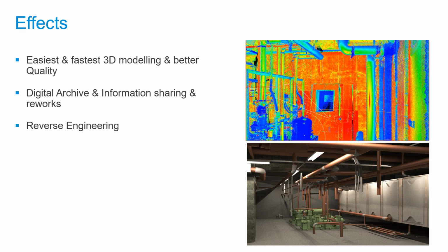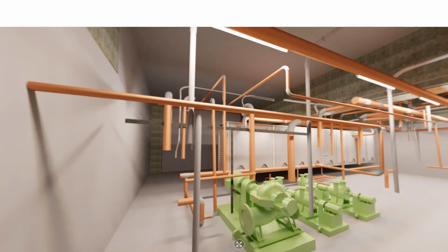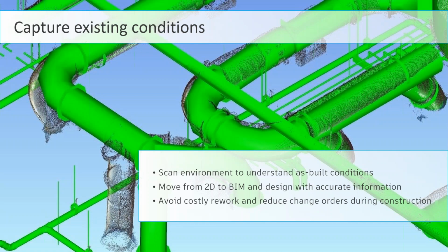But these scanned approaches help you in easily creating a 3D model, and they also help in getting better quality information. So that's the reason you should use this approach for scan-to-BIM projects. That's a 3D cloud rendered image where I've used AutoCAD and Autodesk 3D rendering on the cloud. I could create a 3D panoramic image of that whole basement facility and see how it looks. So that's one output which could be generated for as-built information.